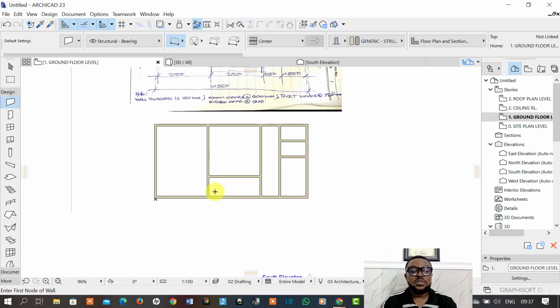So if you want to do estimates, this wall now can give you an estimate of the total area that is wall, and you can divide it by the size of a block to be able to know the number of blocks that you will use for this project. All right, if you have followed me up to this point, then you are doing very well. We proceed to the next level, which is for us to